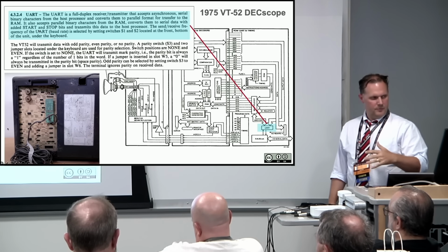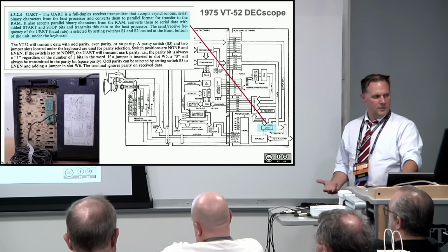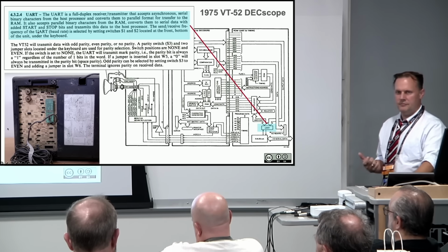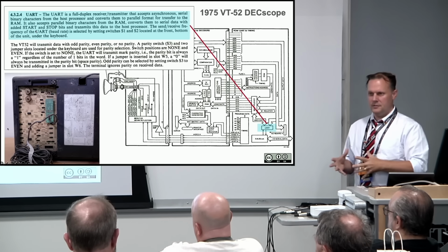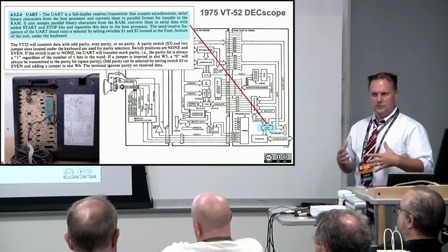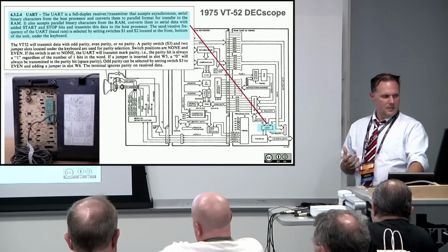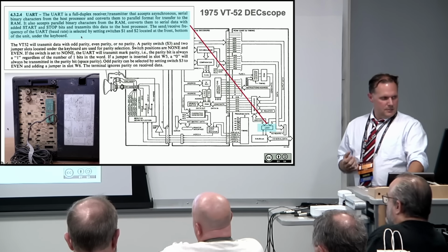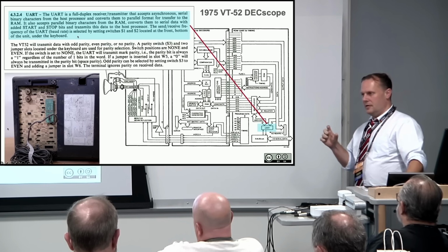I'll talk a little bit more later, but it's a component that adds that start and stop bit that does the framing for you, so the CPU or the processor doesn't have to do it for you. It also has a little bit of buffer if something's running a little bit faster than you or you get interrupted. It can handle that also.